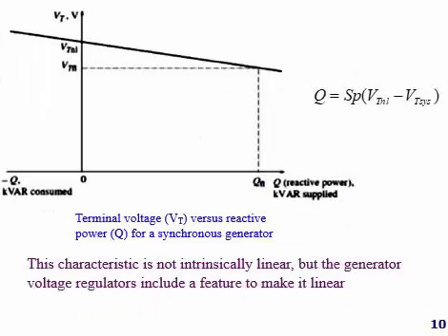The reactive power case is also similar to the previous case, in which there was a slope and then the no-load and system voltages. But in the previous case it was not voltages, it was frequency.